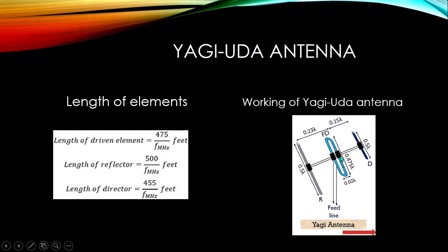How does the reflector work for it? So the reflector, in the opposite direction to that of the director, when accurately placed adds the field in the direction towards the driven element. So this is done in order to reduce the losses due to the back-radiated wave as much as possible. So in order to get the additional gain, multiple directors can be used in the direction of the beam.